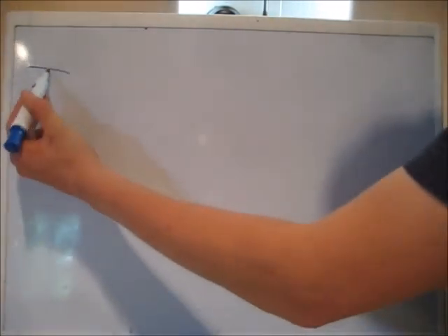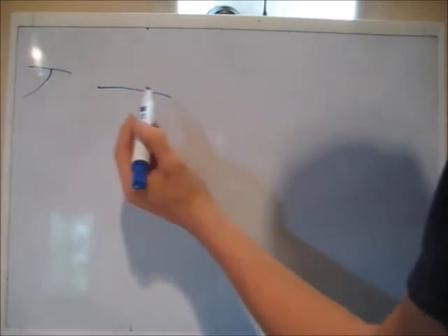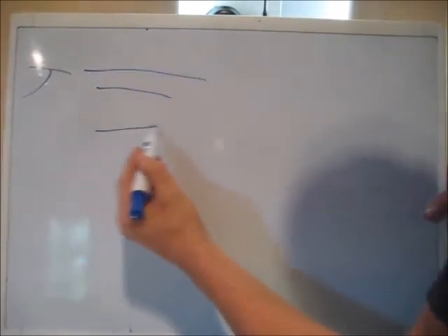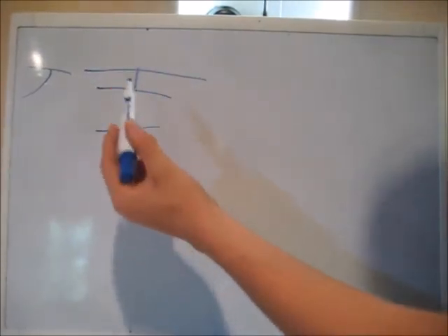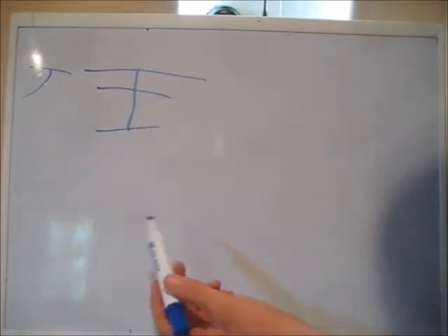So the last antenna we're going to talk about is a beam. A beam works the same way as a dipole with its feed point in the center, but it has 2 more elements. So your dipole is here and has a longer element and a smaller element like this. And that gives it directivity.